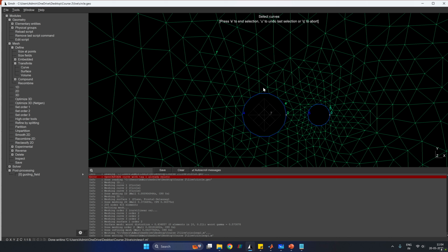So you can model the stress jump on a liquid-liquid interface very easily, even if you have put marker points on this mesh, or you are using a moving mesh. Even if the mesh is deforming, you will get the normal and the tangential components exactly. In that case, those are vector equations for Navier-Stokes.